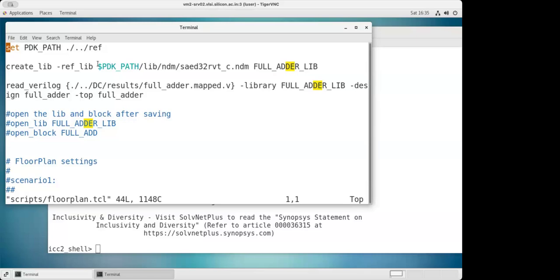In ICC, the first version, all of you can see what is inside the database. Now what they have done is create a single file as a .ndm file, and you cannot just go and see what is inside the database. In layman's language, let us suppose there are 10 different files in the database. They will zip them, convert into binary, and create one NDM file.